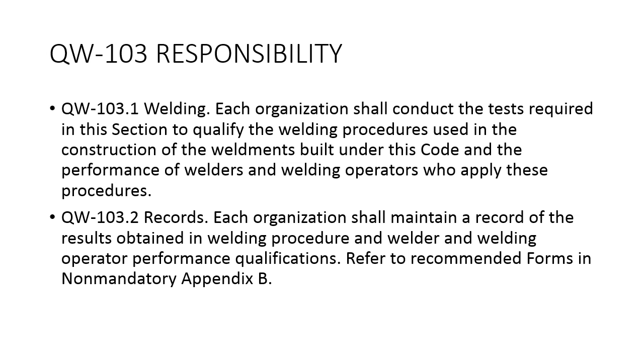QW-103, responsibility. 103.1, welding. Each organization shall conduct the tests required in this section to qualify the welding procedures used in the construction of the weldments built under this code and the performance of welders and welding operators who apply these procedures. Records. Each organization shall maintain a record of the results obtained in welding procedure and welder and welding operator performance qualification. Refer to recommended forms in non-mandatory Appendix B.